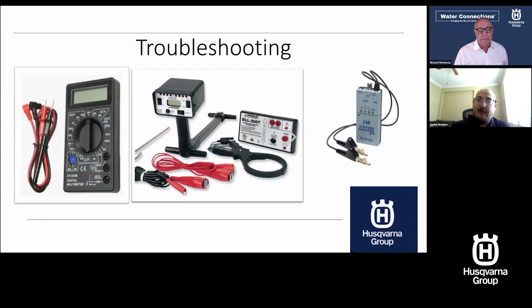Sometimes it's a bad wire connection, it could get worse and worse, and that could trickle down and cause issues with your solenoids themselves, overheating. There's a pintle inside the solenoid. If that freezes up inside there because it overheats, it could cause that valve to stick open, and then you've got water running until somebody gets out there and shuts it off.